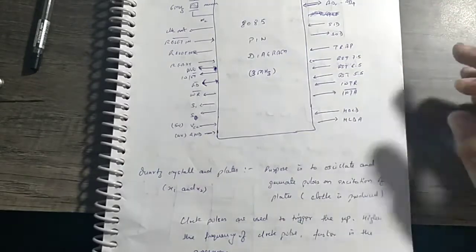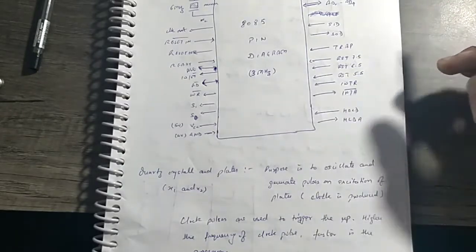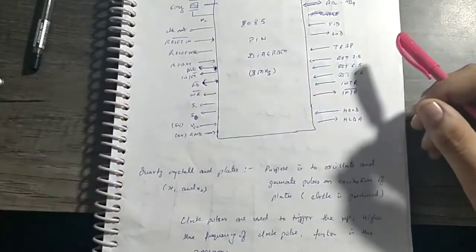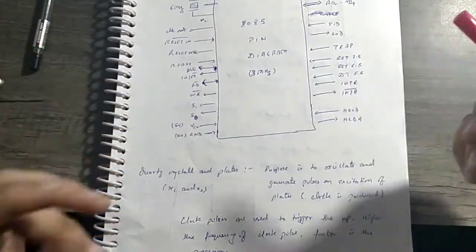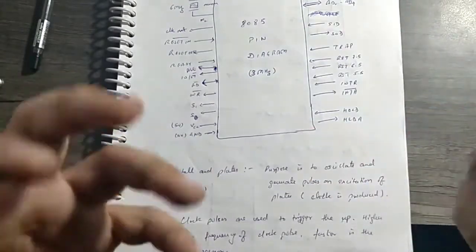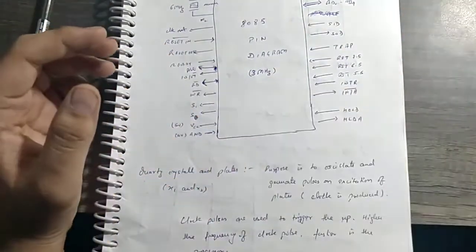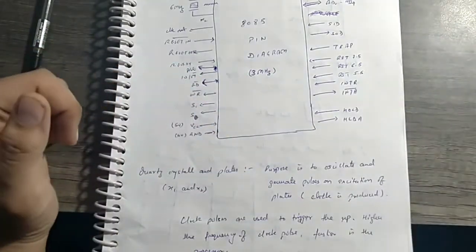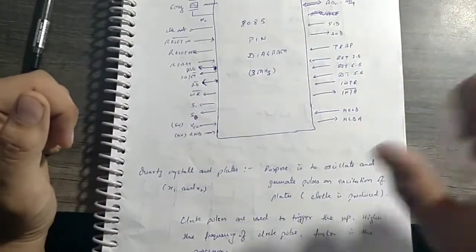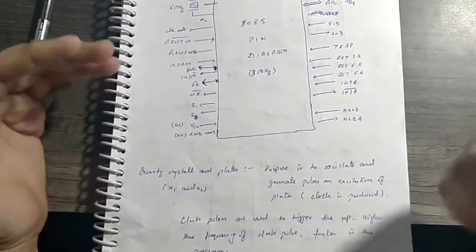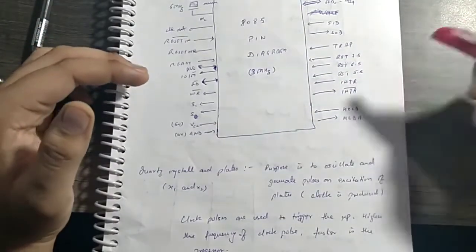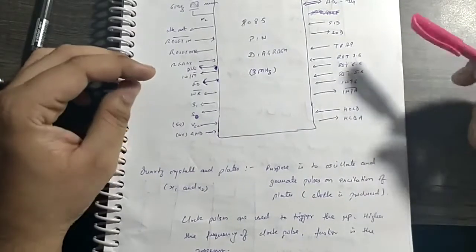We give the acknowledgement to the device, because if our device generates an interrupt, you process the interrupt and solve that interrupt using ISR. We'll be understanding what ISR is and all of these things. Then you send the acknowledgement that your interrupt is received and processed. You send an acknowledgement to the device using INTA bar, which is an active low signal.